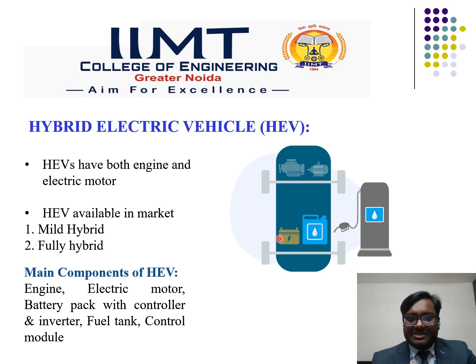Basically, this is a small battery pack, and it cannot be charged from the outside. So we do not have any kind of electricity grid. In BEVs, we do not have any kind of IC engine and fuel tank, but in the case of the HEV, we have both the electric motor as well as the IC engine. But in that case, we cannot charge the battery pack from the outside.